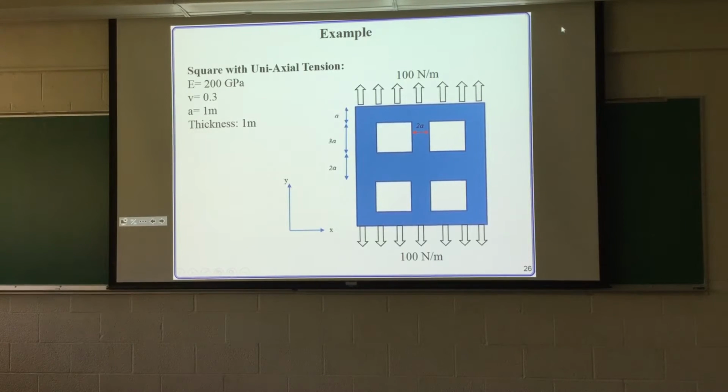So we don't actually have to do a simulation on the entire part. We can cut it into a quarter and then just set boundary conditions in both the x and the y direction in order to run the simulation. And the advantage of this is we don't have to use as many elements, which is especially useful in our class because we have a student edition of Abaqus and we're only going to do 1,000 nodes.